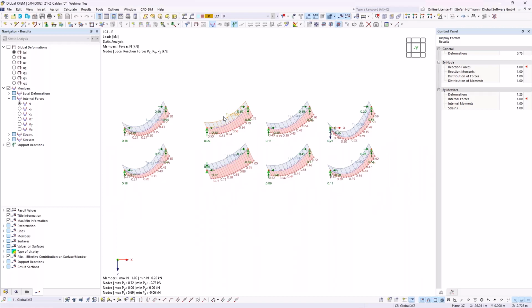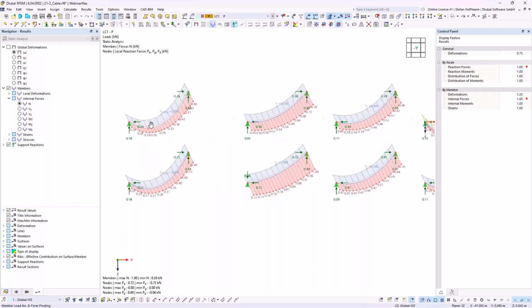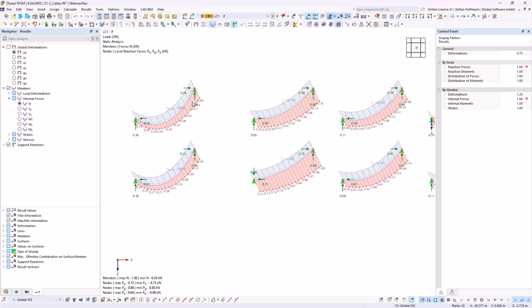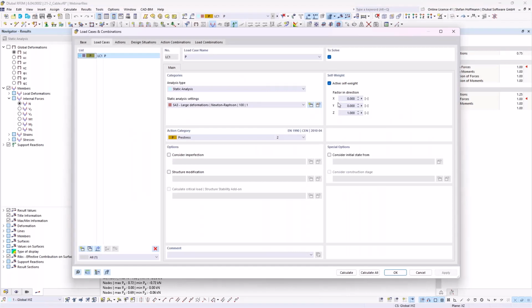So this is a stable construction. We can have it less, this is also stable, this is also stable. And if I would lower it even more, then my structure will become numerically unstable or nonsense. Inner forces will arrive. And this is what this function is doing internally. So it's a minimum force definition to reach a certain convergence or equilibrium. So of course, the dead load is activated for both models.